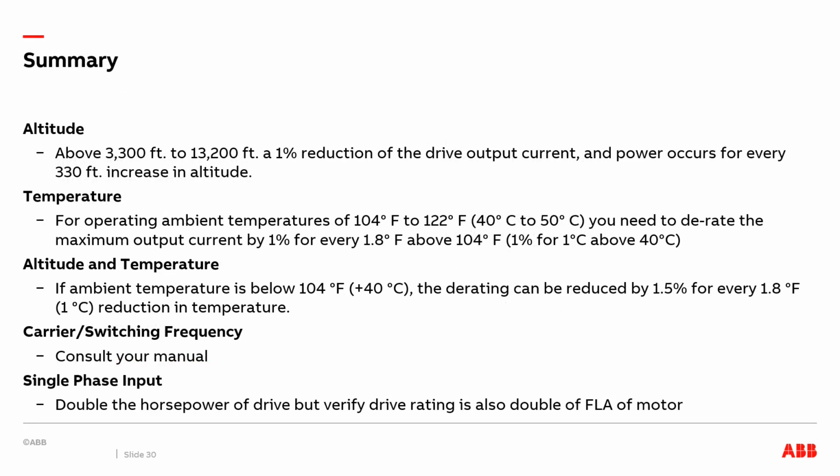Let's do a summary of what we learned here today. First, altitude. Once we go above 3,300 feet all the way up to 13,200 feet, a 1% reduction of the drive's output current and power occurs for every 330 feet increase in altitude.